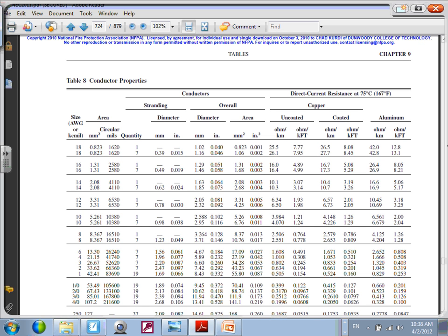You're right. I would say 90% of the owners, I hate to throw that number, 90% of the people that you deal with in buildings are actually dealing with 600 volt or less. So 480 systems. Yep. Yeah, mostly 480 in the US. Only 10% of customers, big customers, refineries and all those guys, make probably 10% of overall utility customers, but they consume a lot of power. Those guys, they give them higher than 600 volts, typically 12.47, 13.8, 4160, and so forth.